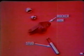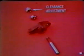Stud-pivoted or pedestal-type rocker arms are made of cast iron or stamped steel. They are mounted on ball sockets atop steel studs. The lock nut that holds the rocker arm on the stud provides the valve clearance adjustment on some engines. Turning the nut up or down raises or lowers the arm to increase or decrease the clearance.